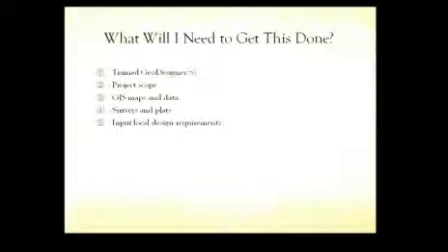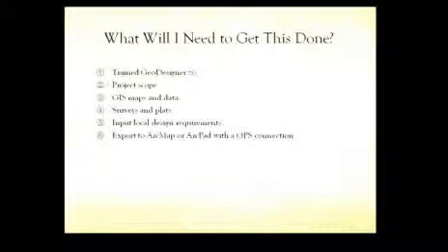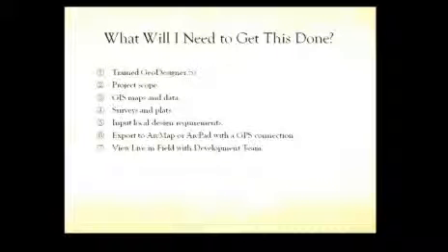And then you can input local design requirements. If you have buffers and setbacks, you're able with this software now to illustrate those in there and set up alerts when you enter those zones while you're walking around on the site, so you can be aware of where you're at, and you export that either to ArcMap or ArcPad. Earlier I said that I used ArcPad, but lately I've been introduced to ArcMap and have a lot more capabilities with it. Both of them will take a GPS connection. It just takes a different type of computer to carry out there in the field.